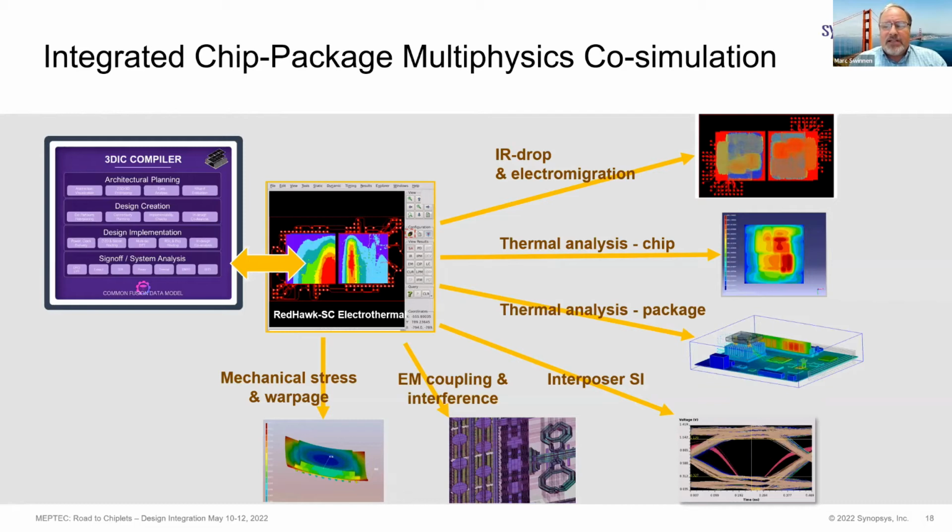The other one, and this hasn't been much mentioned, is the reduced order models that are required. If you're going to do a thermal analysis or a power integrity analysis of your entire system, you can't be dragging around everything at the transistor level. You need to have reduced order models that capture sufficient detail and yet give you a lot of compaction. That's a whole topic that we won't get into here. So apart from electromigration and IR drop, we also have thermal analysis.